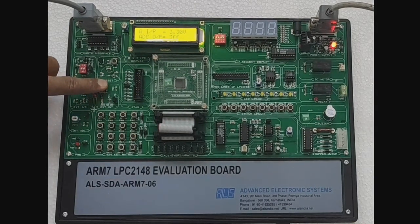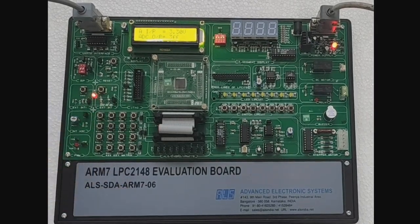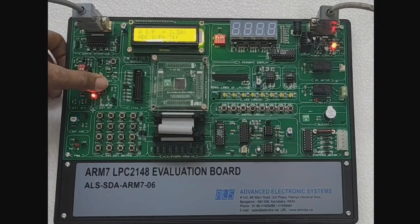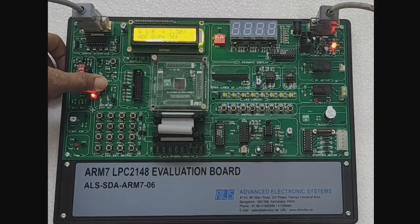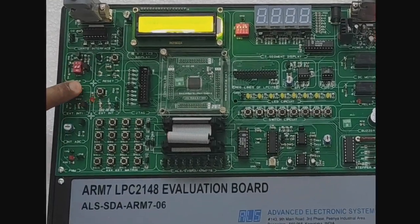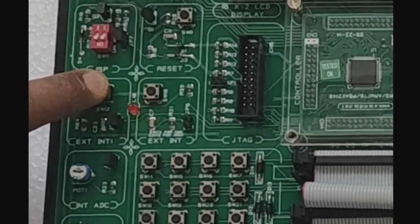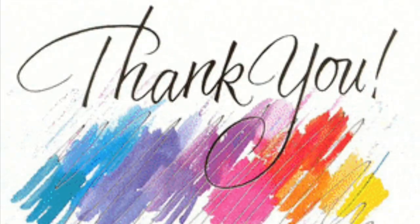The else consists of IO clear and the if consists of IO set. IO set is setting the register and IO clear is clearing the register. So here you can see once you press the interrupt switch, the LED turns off and on.